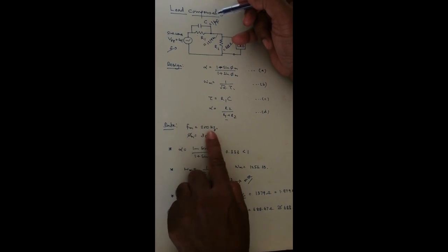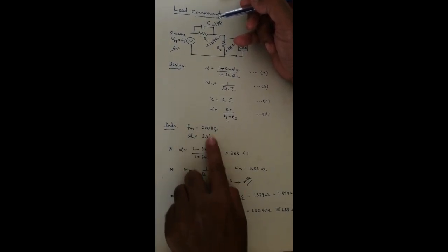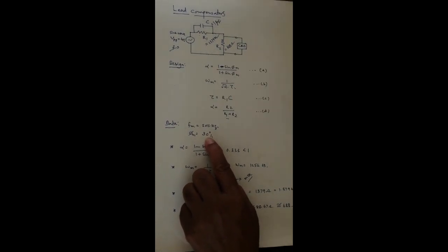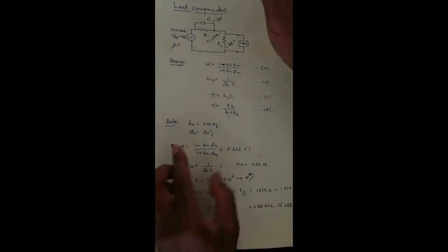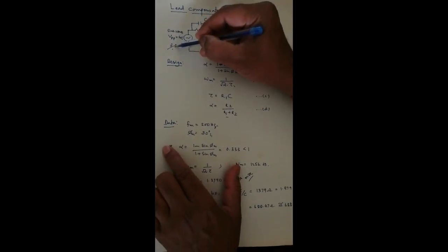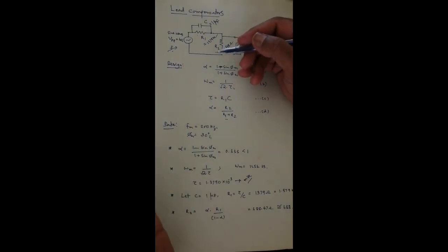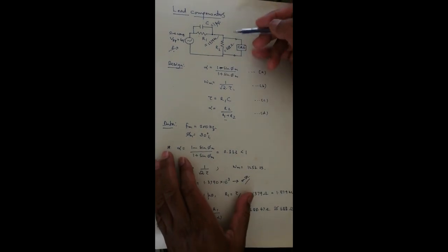When you are going to check your circuit, first you adjust the frequency to 200 Hertz and check whether the phase shift between the output and the input is 30 degrees or not. After that, to obtain your frequency response, as I have mentioned in the methodology, vary the frequency of your input, start from the lowest frequency 50 Hertz till say 5 kilo or 6 kilo Hertz.